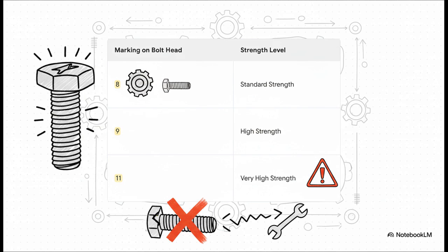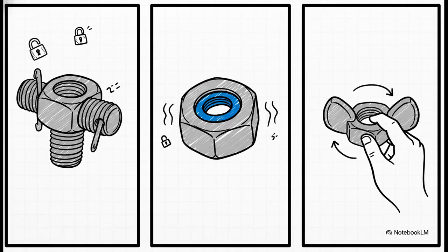An 8 might be fine for everyday stuff, but an 11? That's for super high-stress jobs. Using the wrong grade is a massive safety risk. That's why a good technician will always replace a bolt with one of the exact same grade. No exceptions.